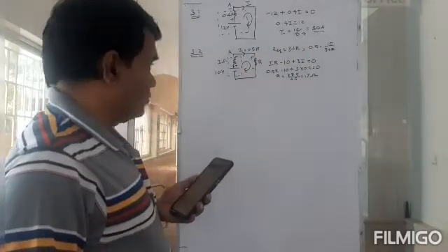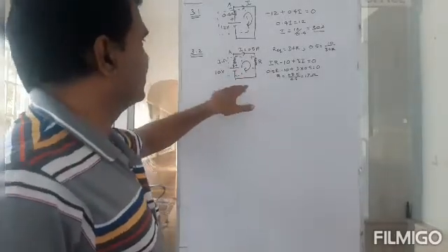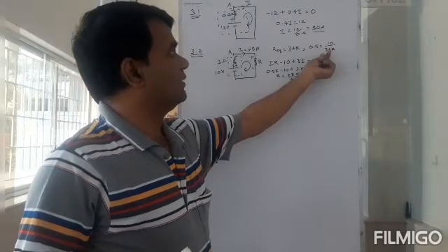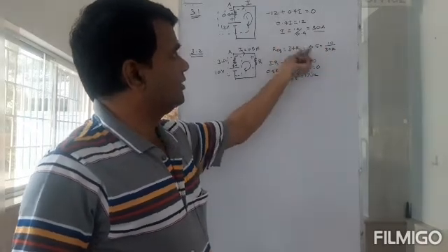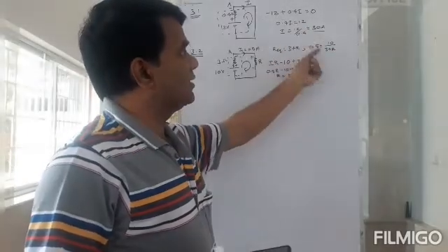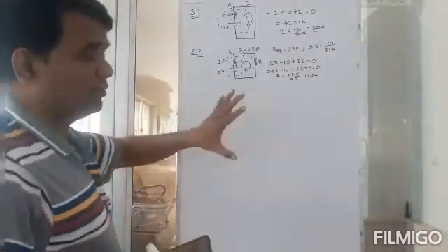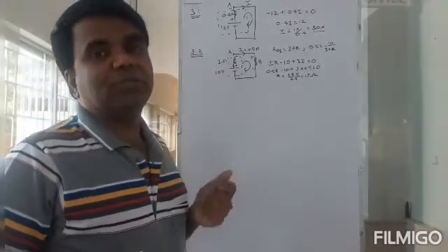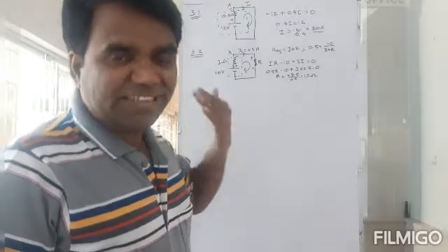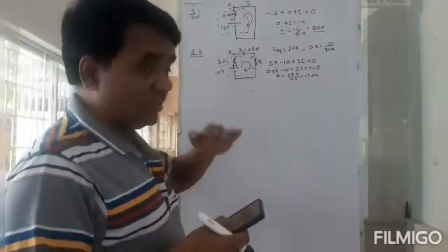It's very easy, right? When you can do it the other way too. So 10 by 3 plus R is actually 0.5. So 3 plus R will be equal to 10 by 0.5, which is 20. So R will be equal to 20 minus 3, 17. You don't even have to break any sweat to do this. It can be very easily done. But then use Kirchhoff's law so that you get practice.